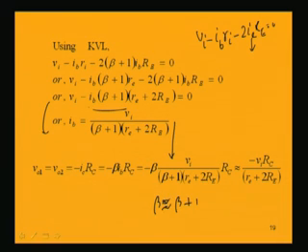So, if we approximately equalize, then we can cancel these two terms. So, finally, we are left with approximately an expression which is minus Vi into RC by small re plus 2 times of capital RE. So, that is the final expression what we get for the voltage gain in the two terminals of the OpAmp output under common mode of operation.